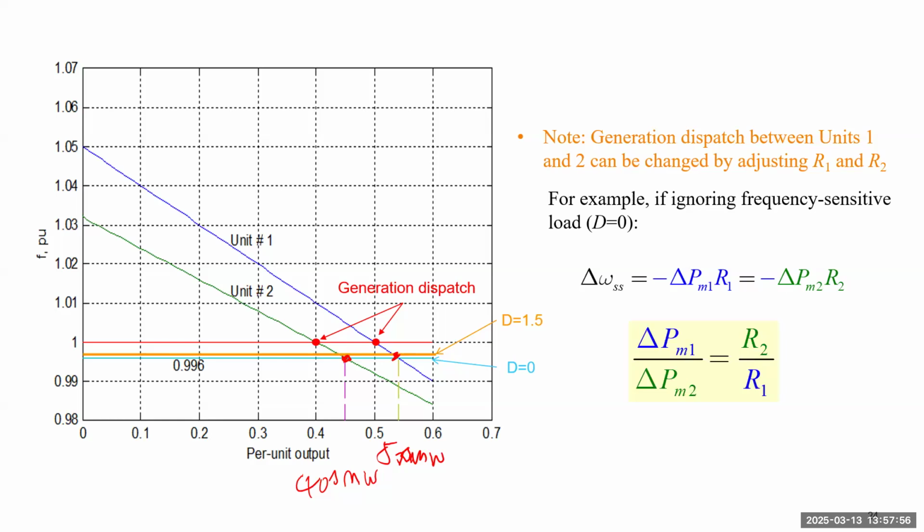Because if you don't set up those R1, R2 properly, their change will deviate from the optimized value. Okay, so you may need to consider the economic dispatch by selecting the R value, unless you don't care. But definitely, if you have an AGC, you can always bring the frequency back to 60 hertz, then don't worry. So this one will temporarily increase maybe your fuel cost during the transition of the load change.